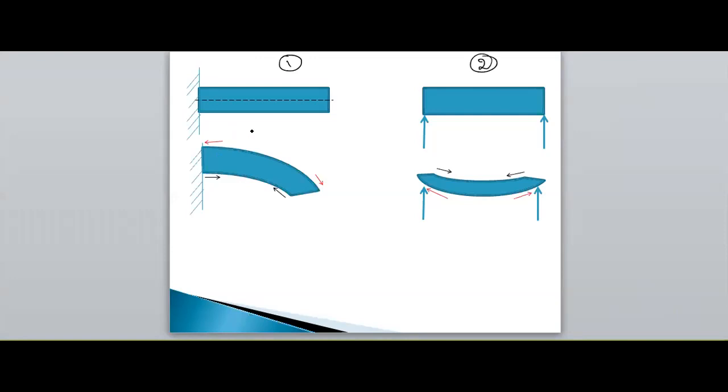When external loads act on a cantilever beam, the topmost layers feel tension and the bottommost layer feels compression. So as y goes upward in a cantilever beam, consider it tensile. As y is taken negative, consider it compression, for a cantilever beam.